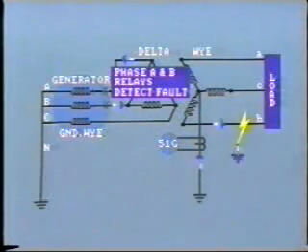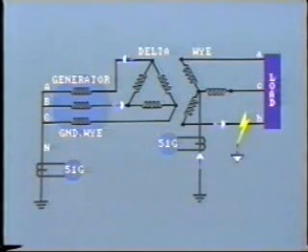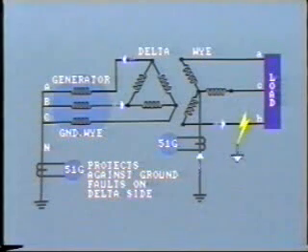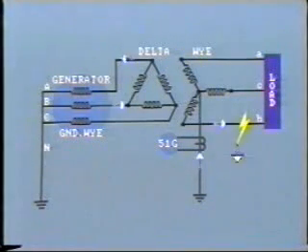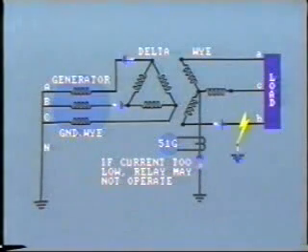neutral of the transformer. An overcurrent relay in the neutral of the generator would protect against ground faults on the delta side of the transformer. Note that if the level of fault current is too low, this relay may not operate at all. But often another path is provided.